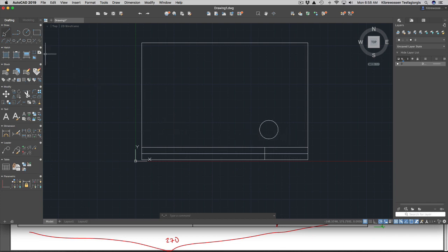If I want to draw a square, as we already mentioned, you start a line command and then type the distance. That's my line, and then I'm going to type another 40 in this direction. Then I move the cursor to this direction and type 40. I haven't skipped the line command to draw those three lines.